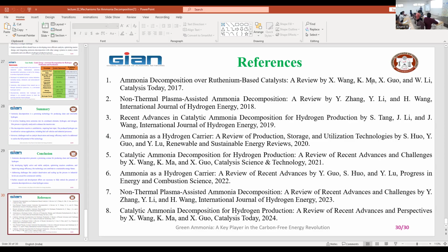Maybe the same thing can be done for our high temperature corrosion here. For the Bombay bridge it is low temperature corrosion, but here you need to do some kind of study for high temperature corrosion. We have a corrosion center at NADC, which can do both low and high temperature. From the fuel tank to the pump it is low temperature. When the fuel is injected into the component, the fuel injector, then the piston rings, piston, cylinder liner, crankshaft, camshaft, even the valves are exposed to high temperature. So we need to do high temperature corrosion studies to understand how ammonia behaves at high temperature.